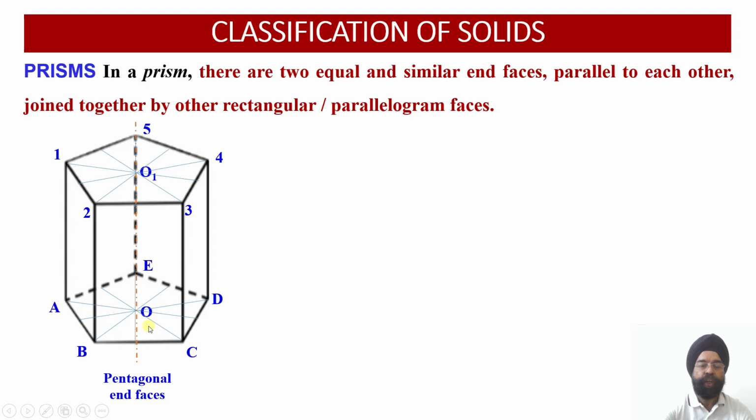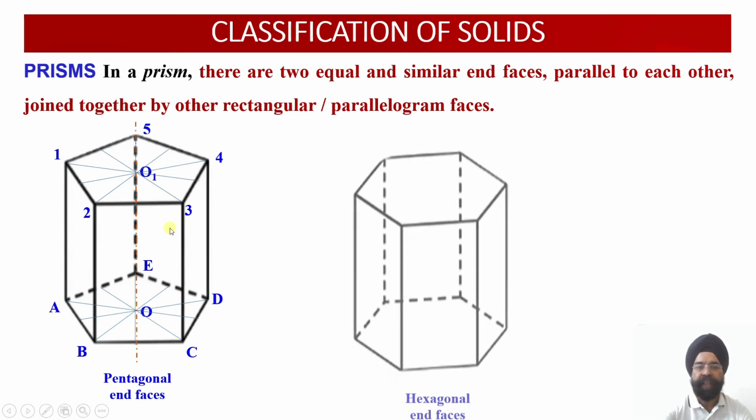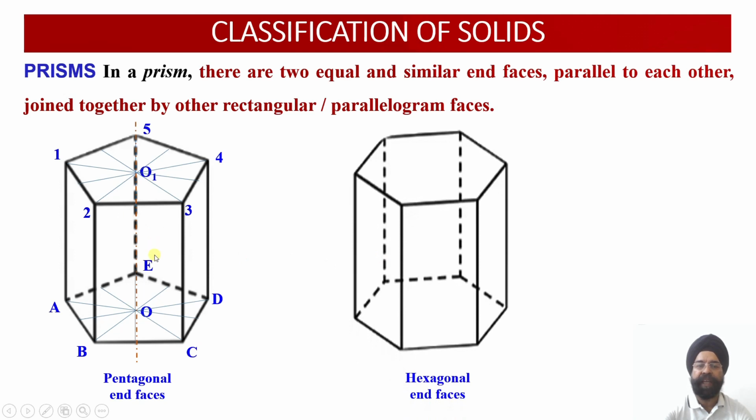So again, 2n plus 2 points have to be dealt with, whether you draw the front view or the top view in any given construction or projection of solid. Since 5 edges are there, n is 5, so 2n is 10 and 2 points for the axis. So 12 points we have to draw. Just like in projection of planes 6 views are required, for drawing 6 views 72 points have to be drawn in projection of solids in case of pentagonal prism.